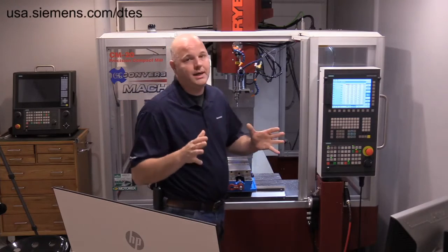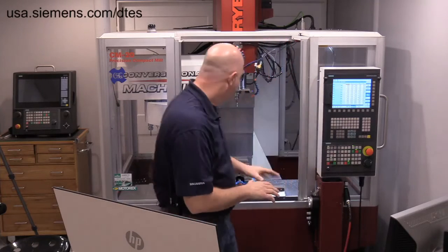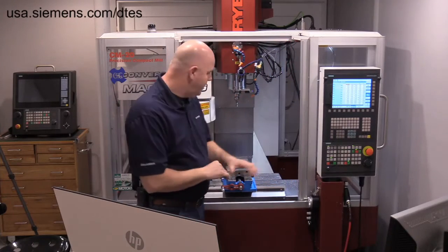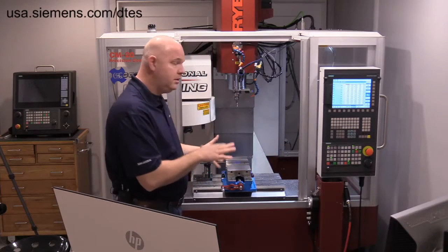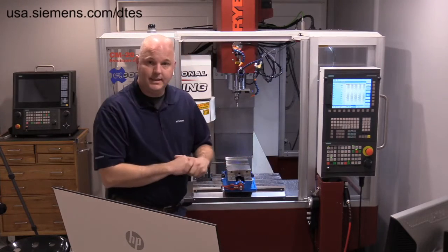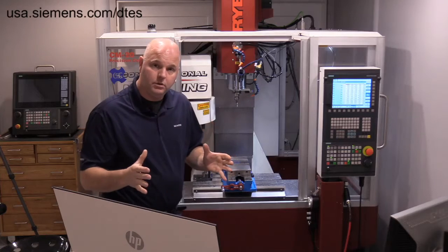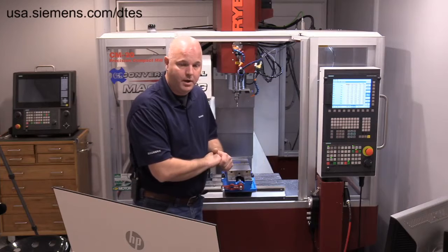Now, there are a lot of processes you do during the setup that you certainly wouldn't be able to reproduce virtually. Yes, you're going to break down tooling, mount tooling up, mount physical vises, edge find or indicate. Those are things you're going to have to do at the physical machine tool. However, there are a lot of processes that you can start to look at virtually way before you get down to the machine. How does my workholding nest on my table? What do my cycle times look like? Am I running into any problems from the part program? The last thing I would want to do is do those things in front of that machine, because now I'm keeping it from running.